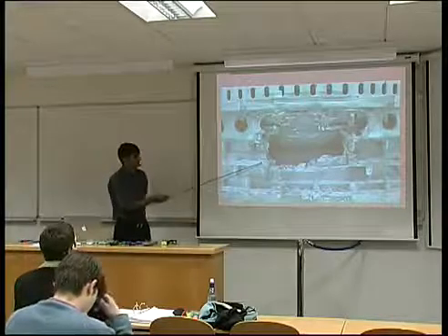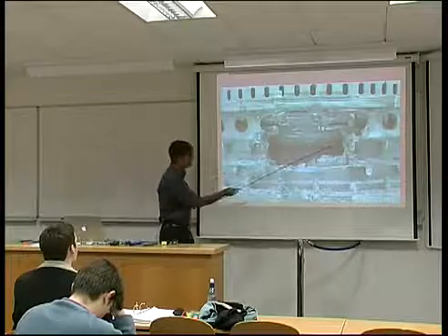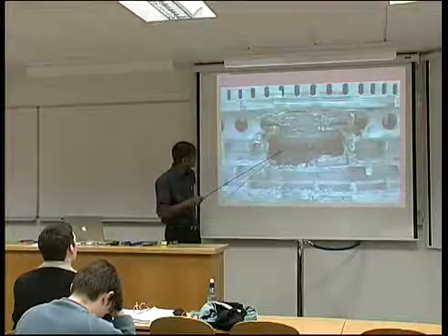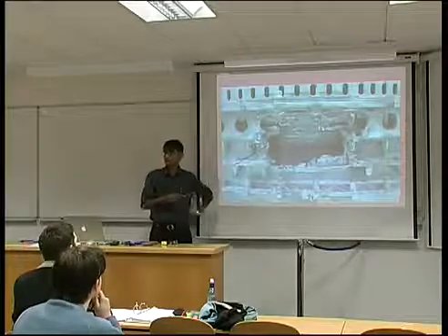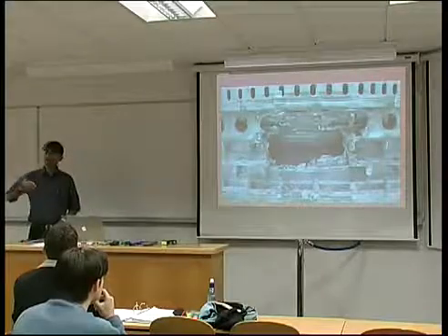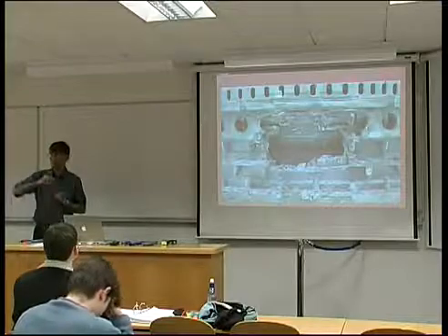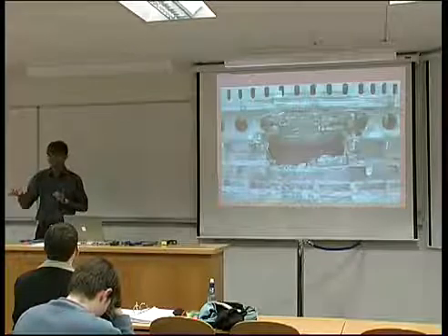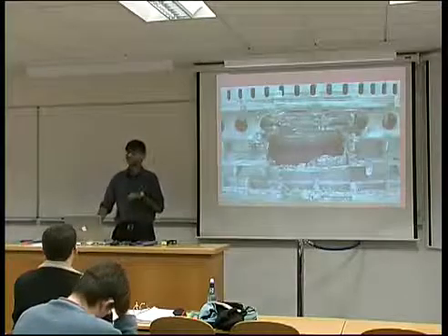This is a consequence of a titanium fire in an aircraft engine, and you can see all these blades have basically disappeared. Okay? And this can happen in a very, very short period of time. So this is the reason why we don't use titanium beyond about 400 degrees centigrade, because if a bit of titanium breaks and rubs against another piece of metal, we will have serious consequences in an aircraft engine.